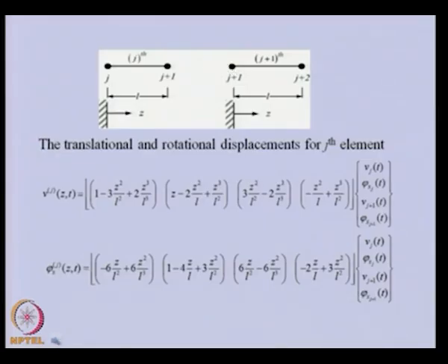And if we want to check for higher order, then we will see that these shape functions may not be compatible for second derivatives. So if we take the derivative of this once more and predict the value at common nodes from these two different elements, we will see that they will not match.